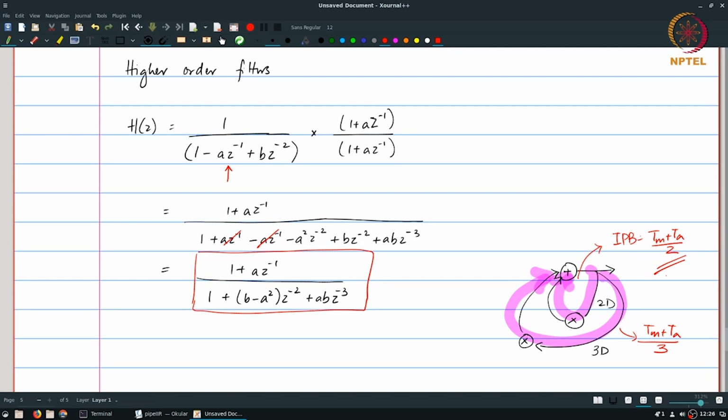The operations are not directly multiplication and addition. In this case, they are addition and comparison. But it turns out that because the addition and comparison follow the same kind of mathematical properties, we are still able to do a lookahead, and a similar kind of reduction in the critical path or the iteration sample period can be obtained in such a case. There are other places as well where this can be done, but keep in mind that it can only be done by exploiting some property such as the underlying mathematics of the system.